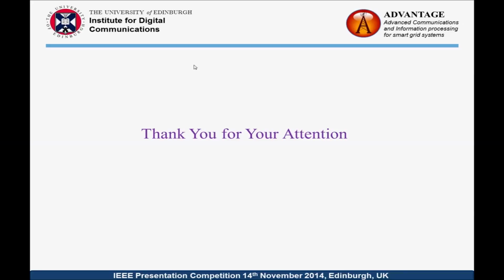I'm not quite in the communication area, so I'm more looking at the power system and what is required from the communications of different types, medium kinds, and things like that. But the first thing I can say is you had so-called 3-9 security or availability requirements for telecommunication, and that's quite bad. Because 5 or 6 nines, 99.99999 reliability, means approximately 1 hour in 10 years, if you look over the longer period, but it's the same as 1 second per day.